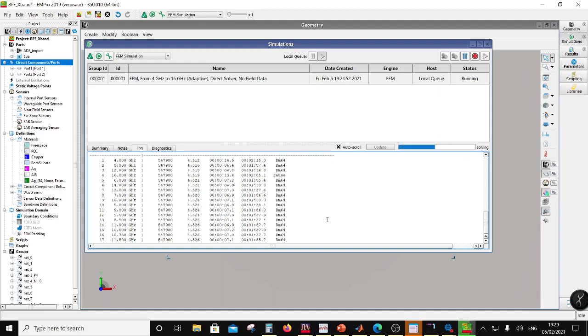Okay, I think it will be done soon. Once it is done, I plot it. Then I'll run this again, putting you on pause, so that I have the field data also. So let this finish. Why is it taking so many points? It is taking so many points because there are resonances here, right? Your G1, G2, G3 were giving you resonators and then the coupling between resonators. So those resonances are why it is putting so many points in this.